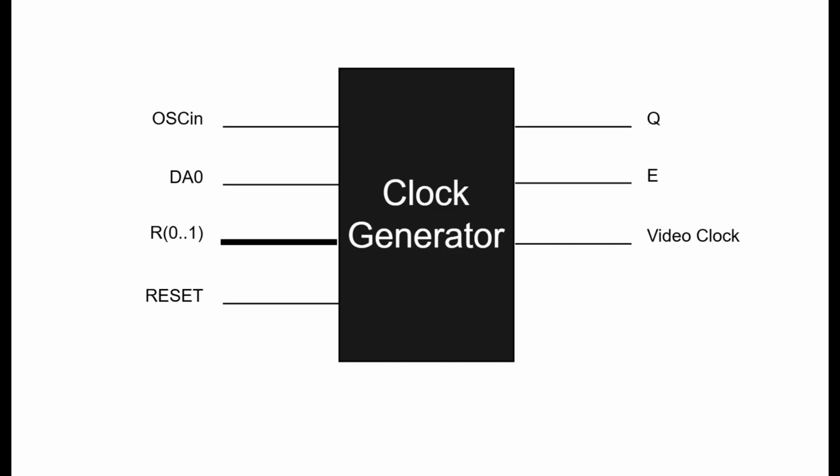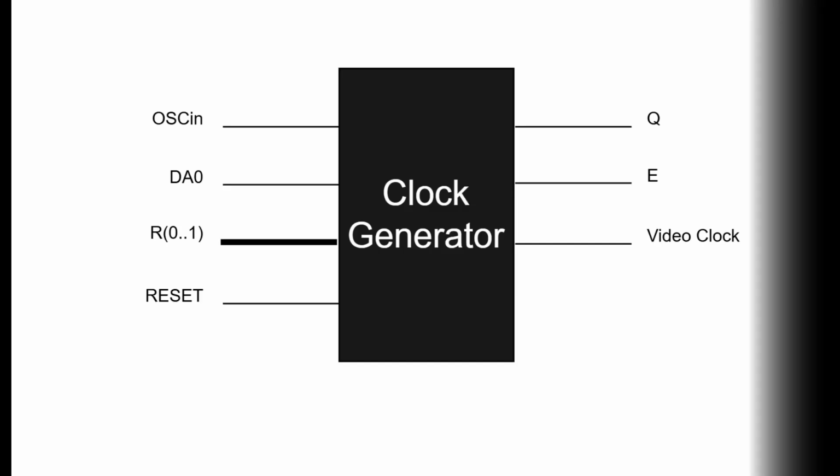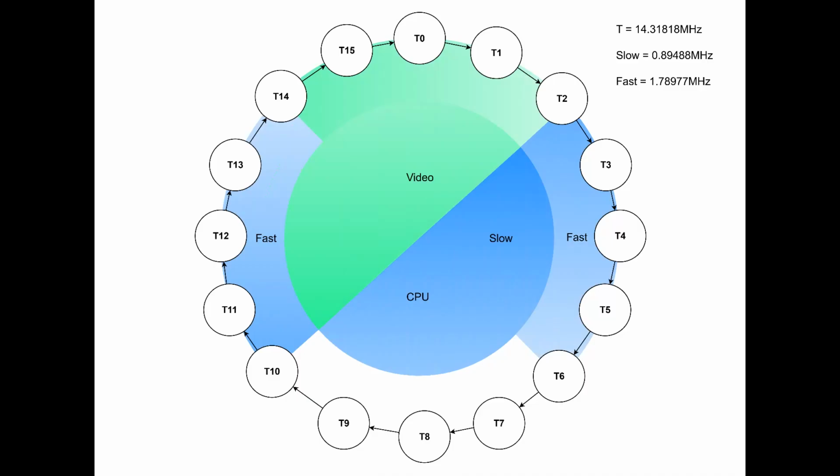The quadrature clock can also be at 1.8 MHz depending on R, and the change between normal and fast just needs managing. Thankfully, a state machine that accurately describes all of this behaviour is defined in VHDL already, along with the rest of the functions of the SAM.